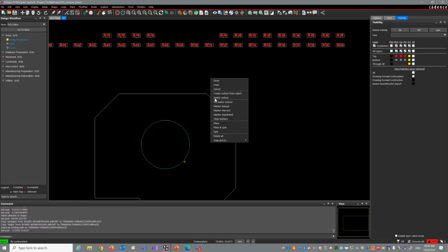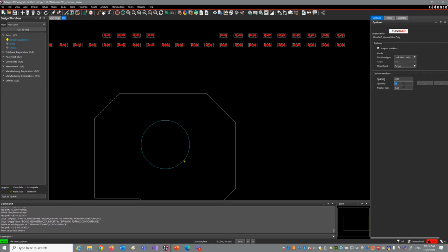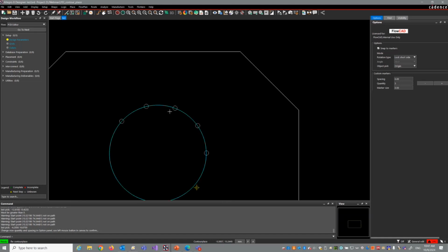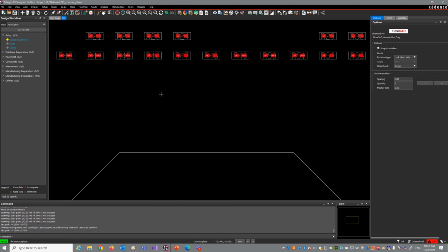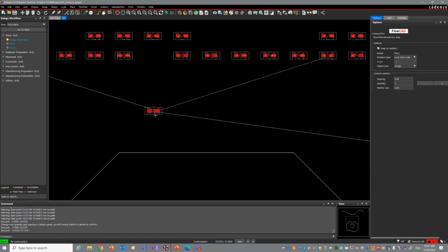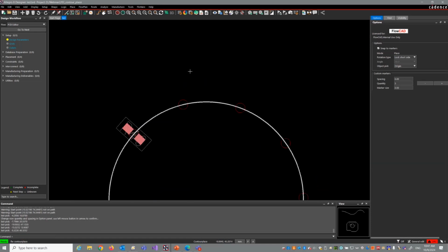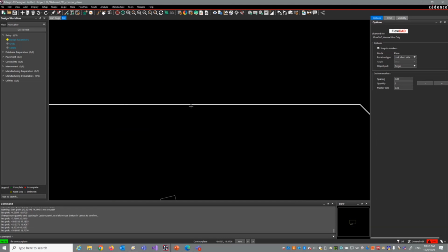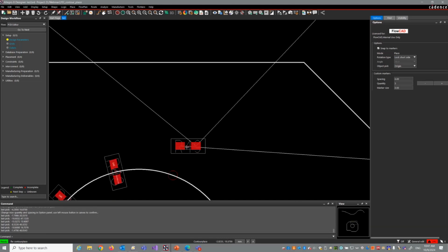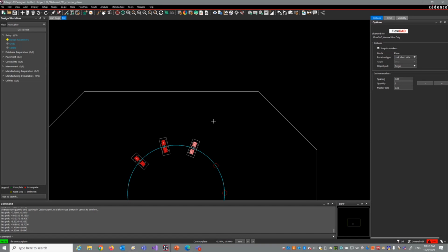We go to marker equidistance. We specify 5 markers. Click here. Now these are our snap points. Left click to confirm. Now go to place. Pick a component, attach it to cursor, place nearby, and now click nearby, and you can see how the application now snaps to that contour placement.